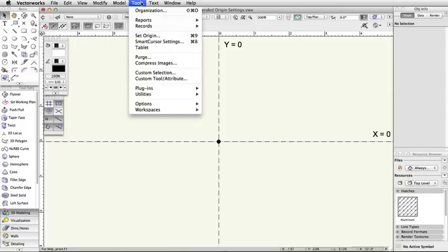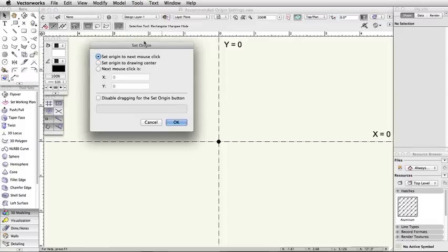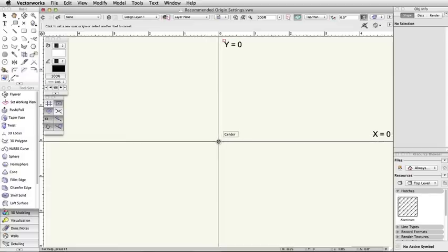If you need to work with large coordinate values, such as a national or world scale, you want to make sure your objects are close to the Vectorworks internal origin, and that you change the user-defined origin to maintain the needed coordinate values. The user-defined origin can be thousands of kilometers offset from the internal origin.